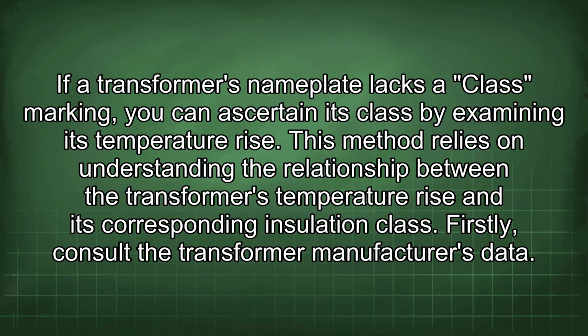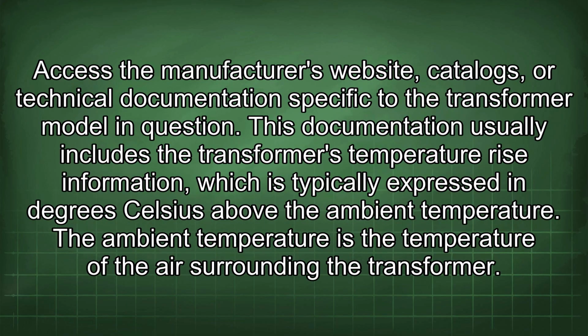Firstly, consult the transformer manufacturer's data. Access the manufacturer's website, catalogs, or technical documentation specific to the transformer model in question. This documentation usually includes the transformer's temperature rise information, which is typically expressed in degrees Celsius above the ambient temperature. The ambient temperature is the temperature of the air surrounding the transformer.